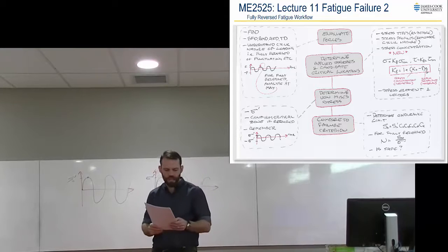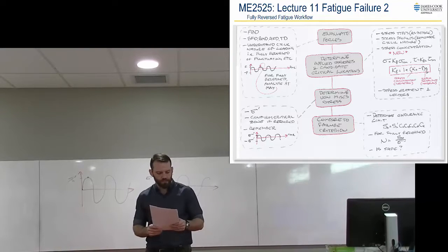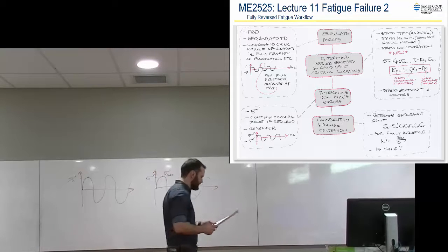And then I look at my SUT, and so you've got the black lines of steel and the dashed lines aluminium on the left. And so if you have different ultimate tensile strengths, the higher the tensile strength, the closer to 1 that notch sensitivity is.